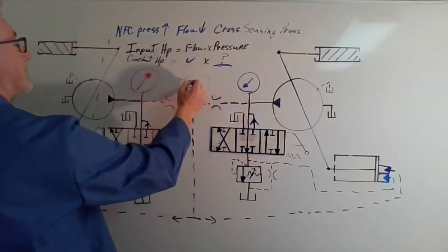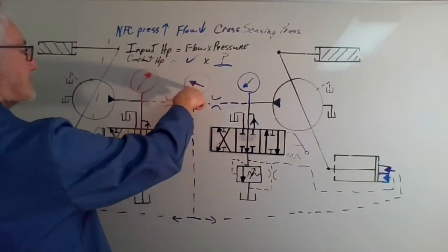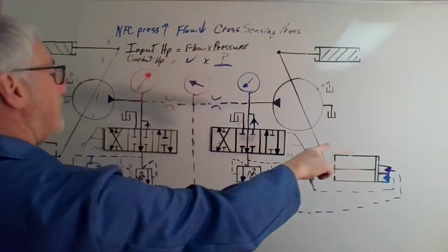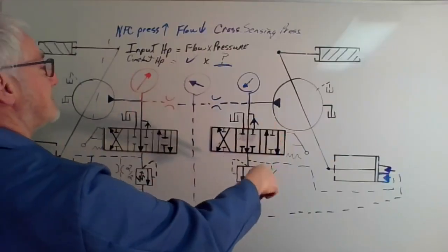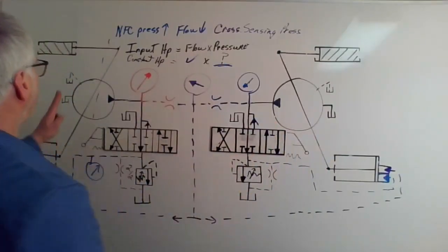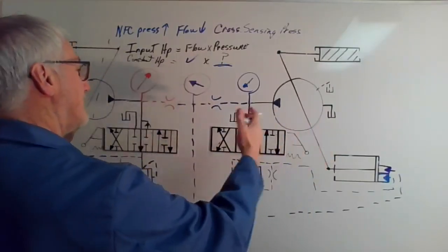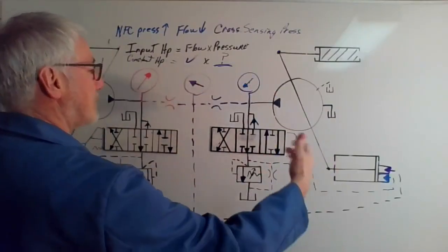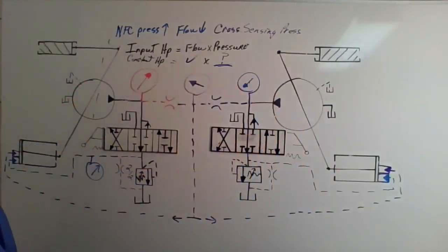Always be talking to each other to come up with whatever that pressure is. And that pressure is ultimately working on both swash plates, which will take, even if I load this one, this one's heavily loaded, that one, not so much. It will try and de-stroke both of those pumps.